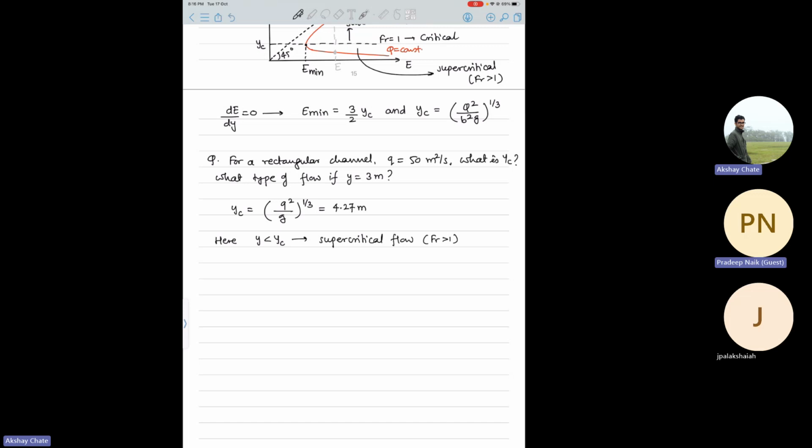And the depth has to be small in that case. If the Froude number has to be more, the depth has to be less, so less than yc, if you have that flexibility in your hand. But in many cases it may not be possible. So in that case, you can manipulate V or your flow rate, because velocity is nothing but flow rate divided by area, right? So you can manipulate the area or the y direction flow depth, that is good. Otherwise, you can manipulate the flow velocity also, if possible. So both factors can govern the upstream Froude number.